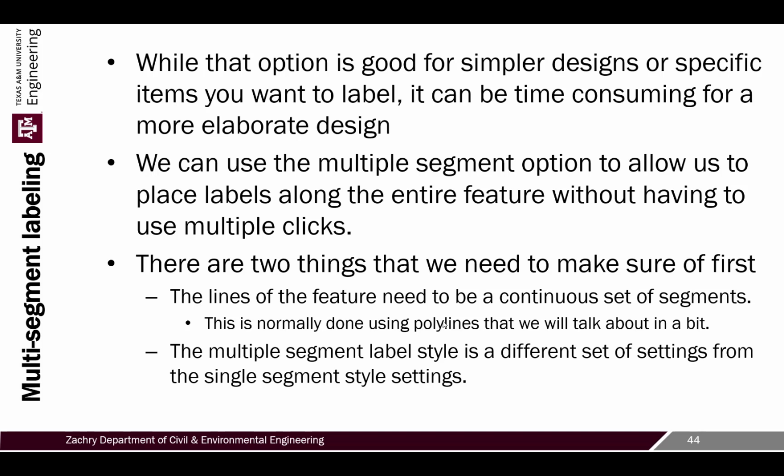But there's two things that we need to make sure of first. First off, the lines of the feature need to be a continuous set of segments. And the way you normally do this is you're either going to have a feature line that has it set up that way or a polyline. And we're going to talk about creating polylines in a little bit on another day, but you'll create a polyline.